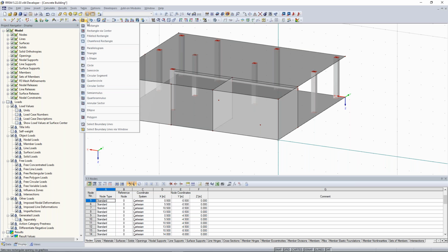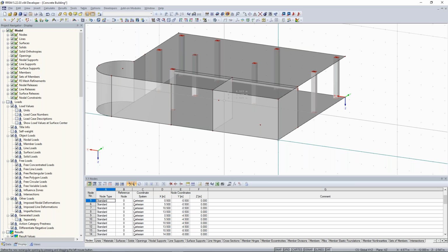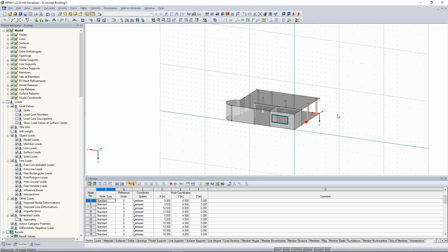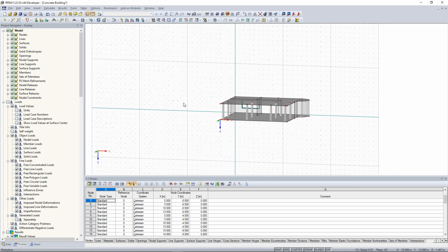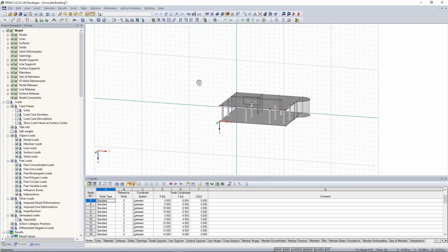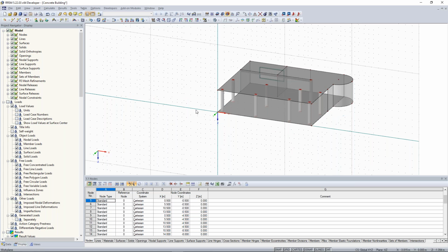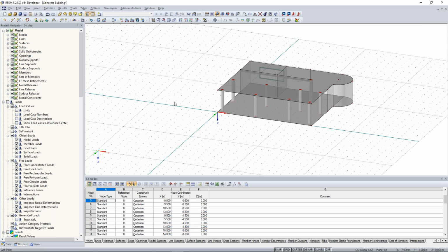Create here rectangle opening next to the surfaces and choose here these two nodes, and I've created this opening here. Okay, then I preset my set of origin back to my original coordinate system and change the work plane to X, Y. Good, so much to them.